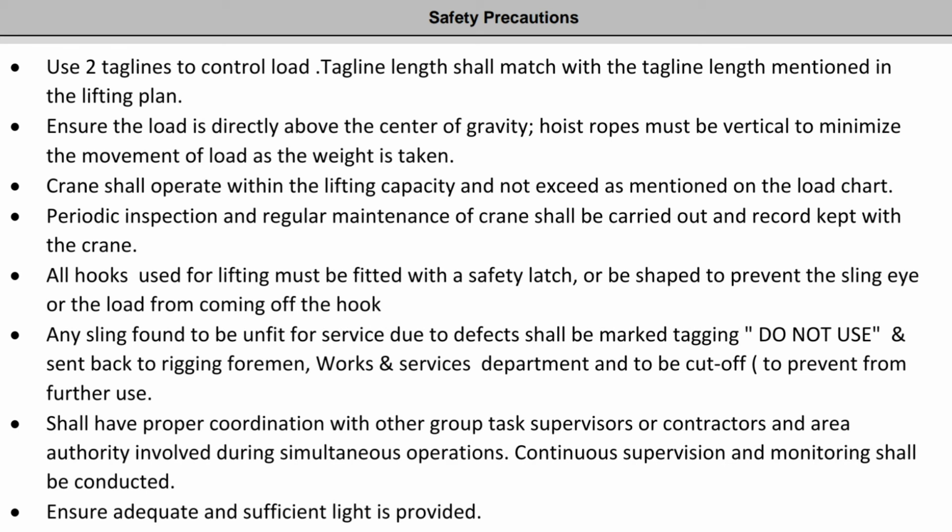Ensure the load is directly above the center of gravity. Hoist ropes must be vertical to minimize the movement of the load as the weight is taken. Crane shall operate within the lifting capacity and not exceed what is mentioned on the load chart. Periodic inspection and regular maintenance of the crane shall be carried out and records kept with the crane.